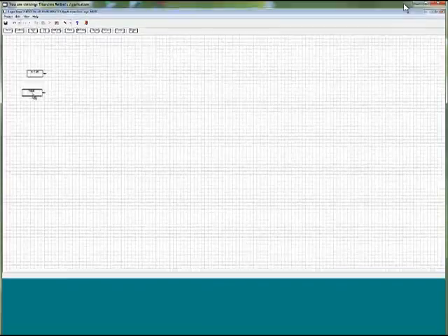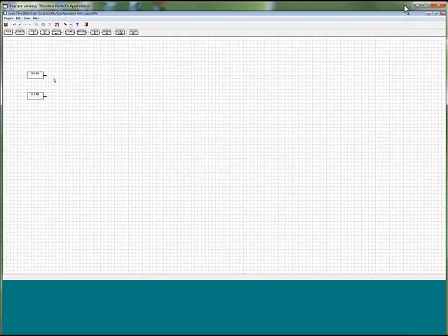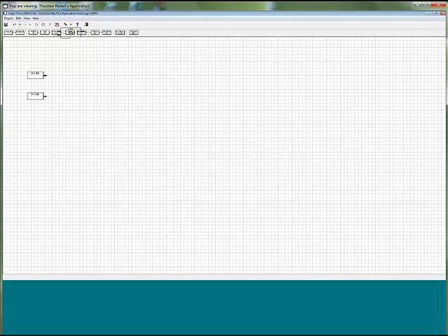You can see our plugin software, which looks similar if you work with ETS 3, 4, or 5. The first step is we click on our input via drag and drop. Now we insert an input, a next input, maybe a second input. Then we use a gate, click on the gate, via drag and drop, and we need a minimum of 1 output.